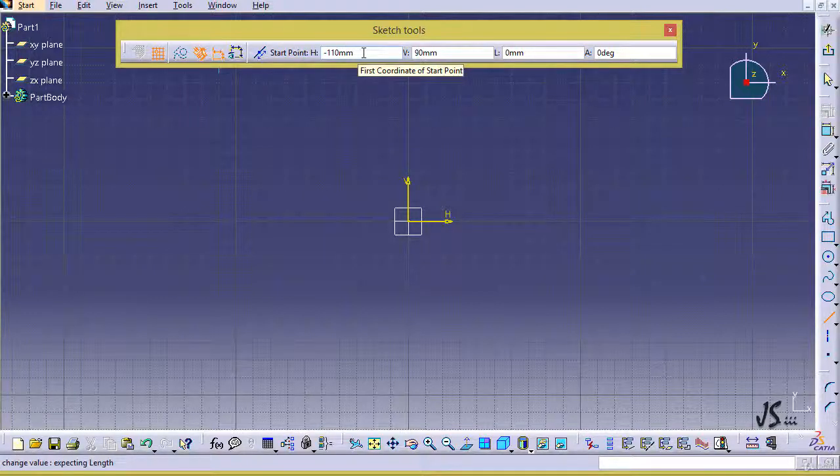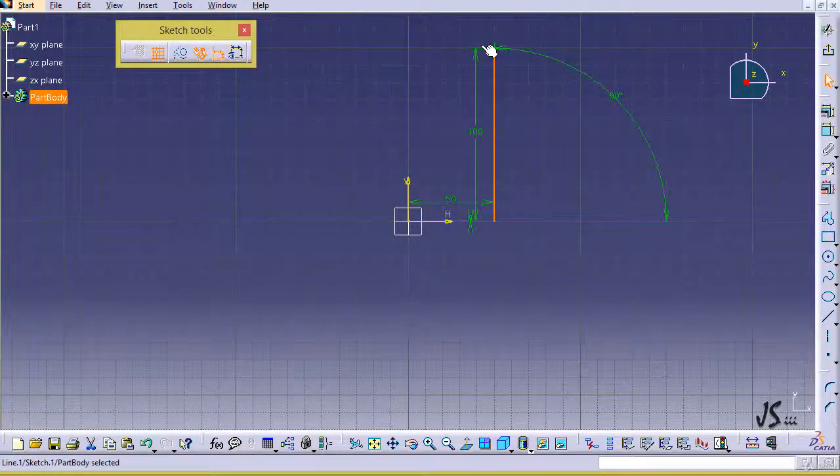And you can see that I can start from a point with horizontal and vertical coordinate of something. And I can add a length for that and a degree for that. Let's say that I'm going to start from 50, 0. So this is going to be the start coordinate. And I'm going to have this something like 100 millimeters, and the angle is going to be 90 degrees. So I hit enter and the line is going to be created for me.